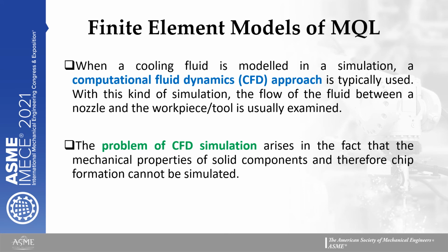When it comes to the modeling of the MQL machining process, the computational fluid dynamics approach is used. With this kind of simulation, the flow of the fluid between the nozzle and the workpiece or tool interface is usually examined. The problem with CFD simulation is that the mechanical properties of solid components and therefore the chip formation cannot be simulated.